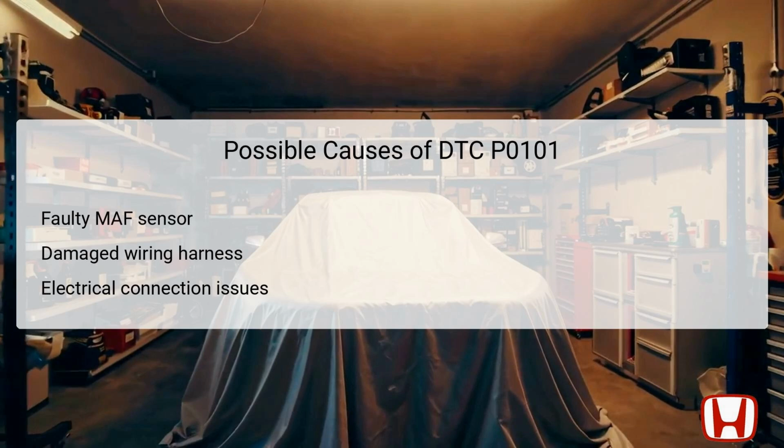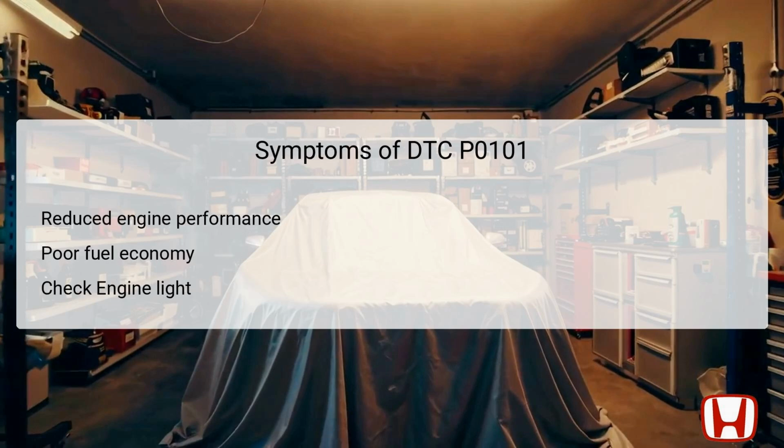In some instances, the issue may even stem from a problem in the Powertrain Control Module, PCM, which interprets the signals from the MAF sensor. Thorough examination of each of these potential causes is crucial for effective troubleshooting. Drivers may experience various symptoms if the DTC P0101 is triggered.